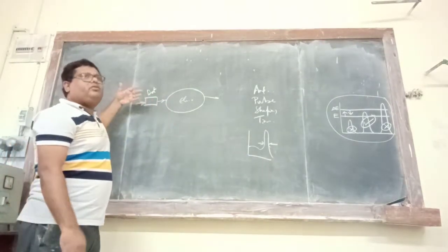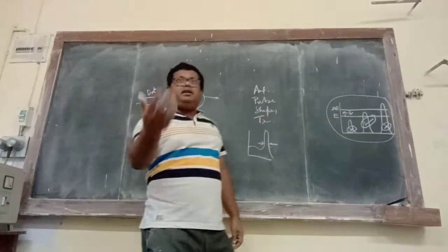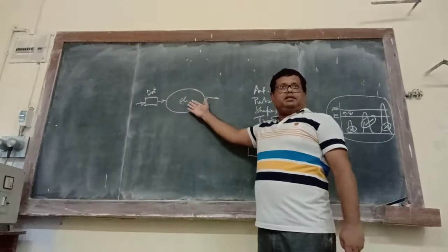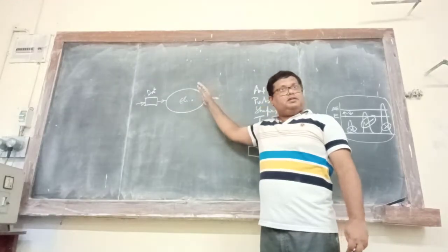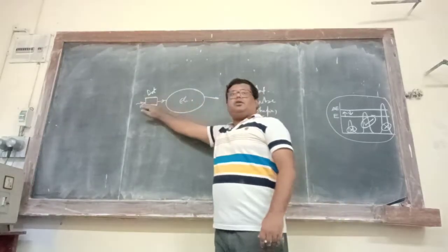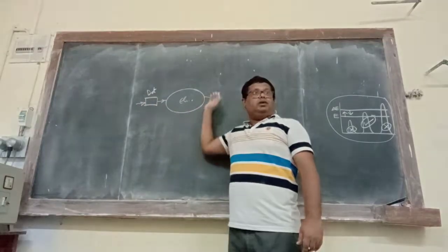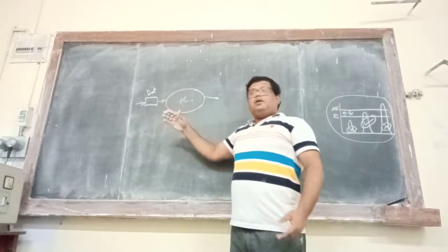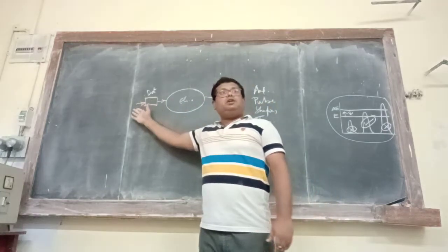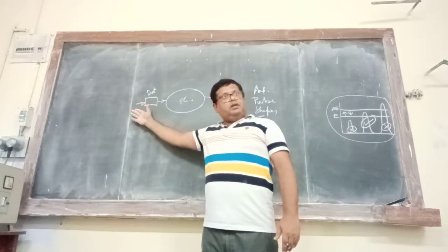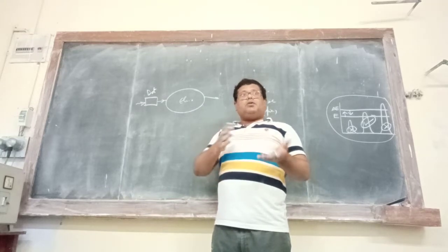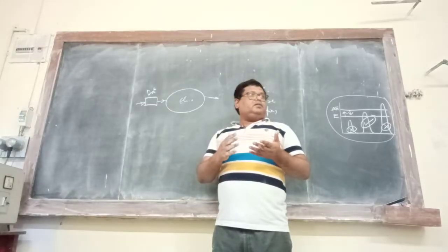Why? Because the detector will say, I have already accepted one valid particle, I have given you a valid pulse, and the system is now processing it. So unless the system completely processes, it will not record. This is the way the system works. So if you have a very large pulse shaping time, it takes a large time. So in a way, you are losing a lot of data. You understand? Large dead time, in fact. So doing an experiment means compromising the stuff, which is important.